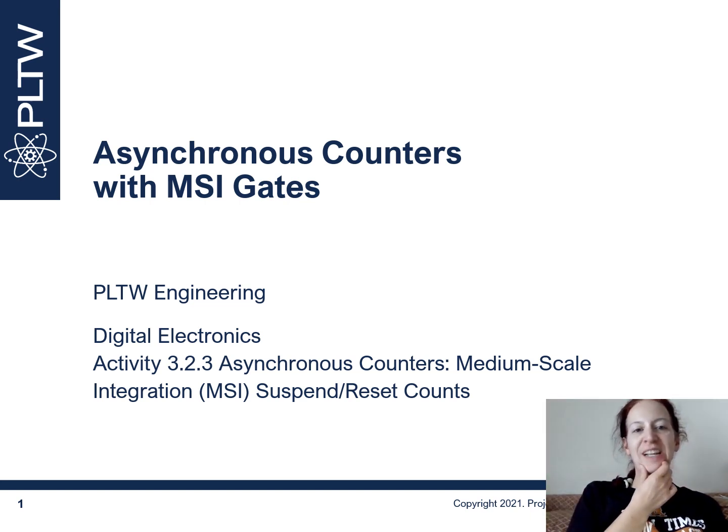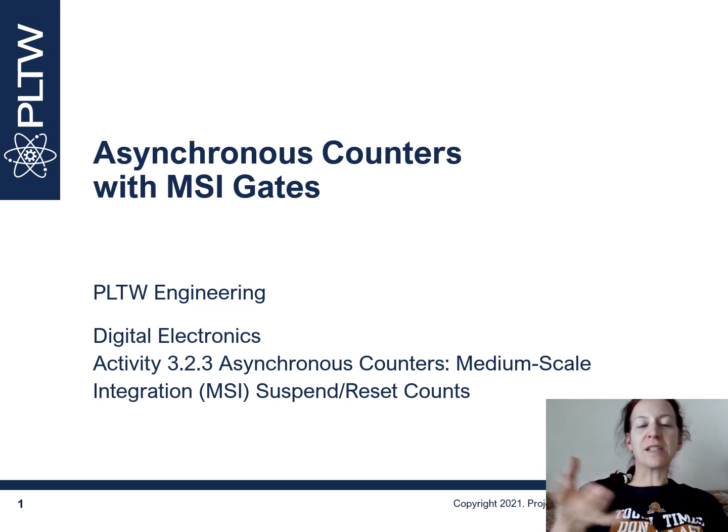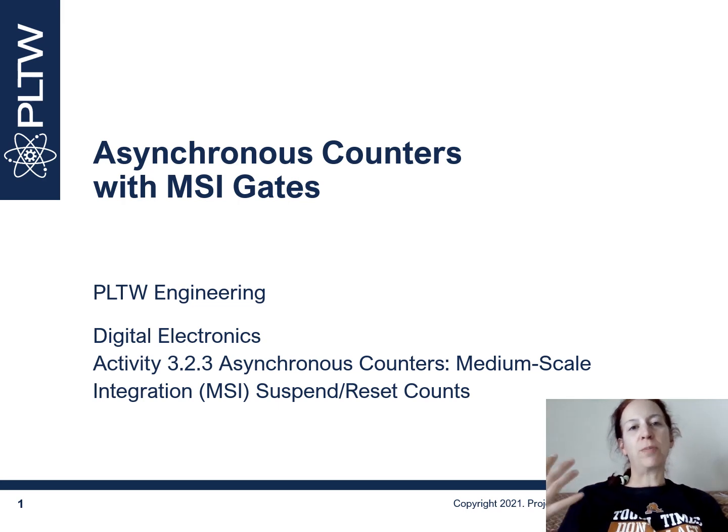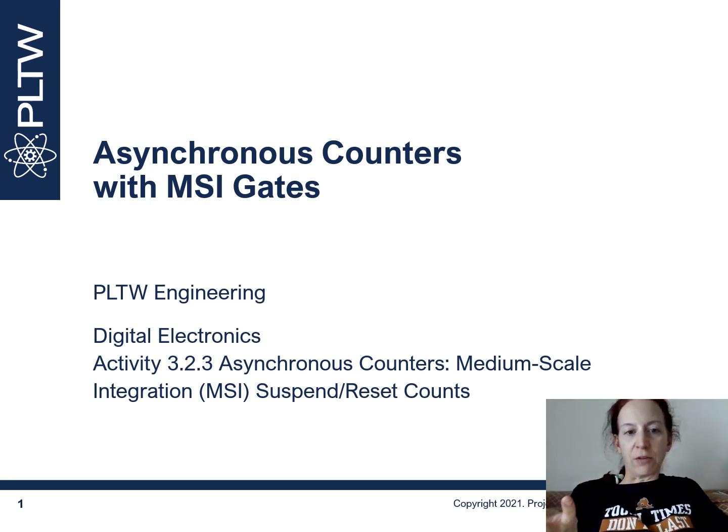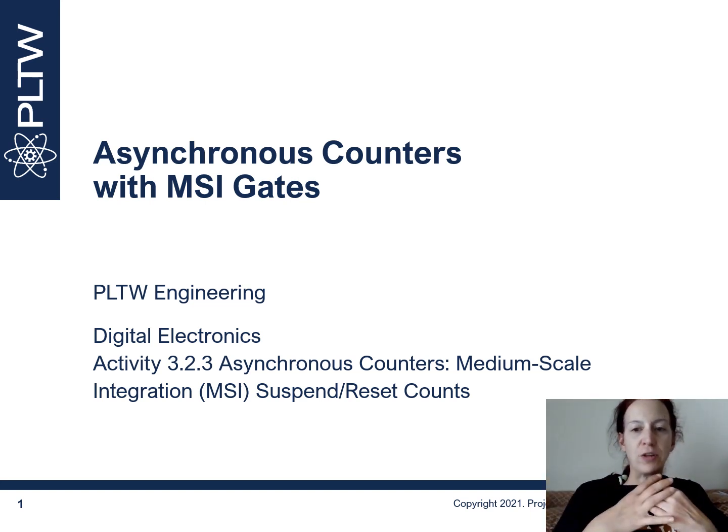It's pretty short and it covers asynchronous counters with MSI gates. So if you remember, MSI stands for medium scale integration. And pretty much what that means is instead of designing your counter with a bunch of flip-flops, you can actually purchase one IC, that's integrated circuit, little black chip, that will function as an asynchronous counter. So I think right off you can see where there's a benefit to being able to do that.